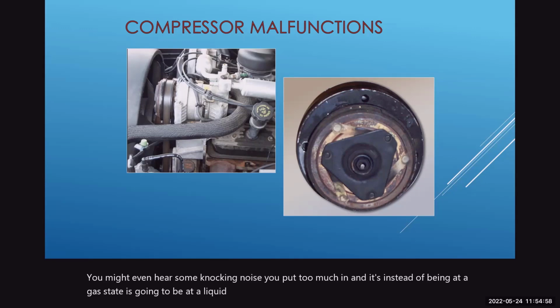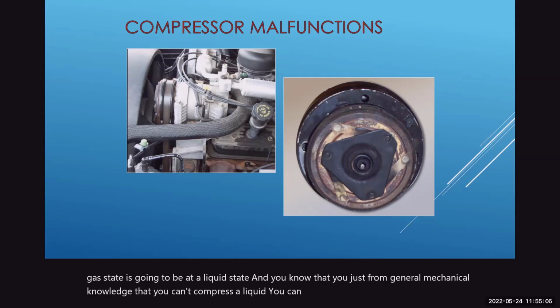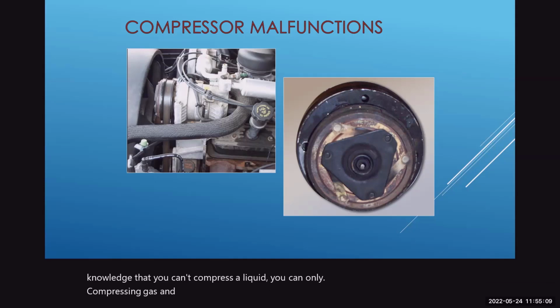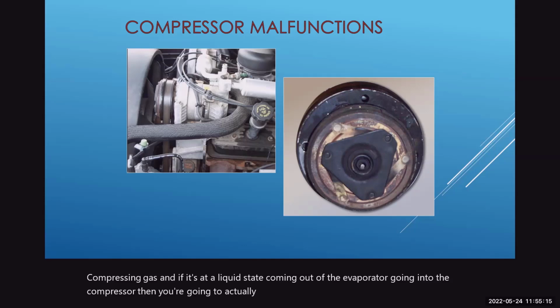And you know from general mechanical knowledge that you can't compress a liquid. You can only compress a gas. If it's at a liquid state coming out of the evaporator going into the compressor, then you're going to cause damage to that compressor and all the internal parts of it also.